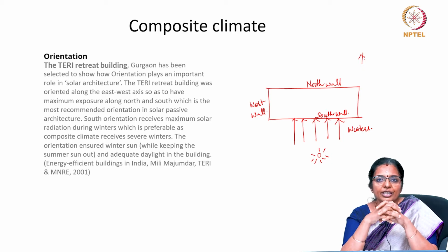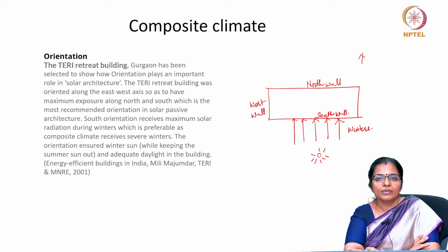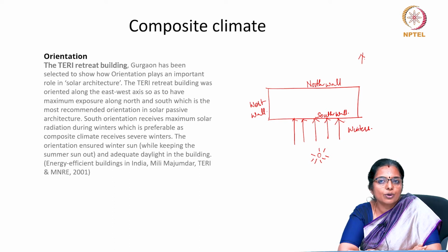Appropriate building construction in tropical and subtropical regions for cold climates must ensure orientation slightly east of south, that is favored, because exposing the unit to morning and afternoon sun and enabling the building to heat during the day will be beneficial. When we look at wind orientation, buildings should be arranged so that they benefit from summer winds, because this season is usually humid and a proper cross ventilation is required for cooling and hygienic reasons.